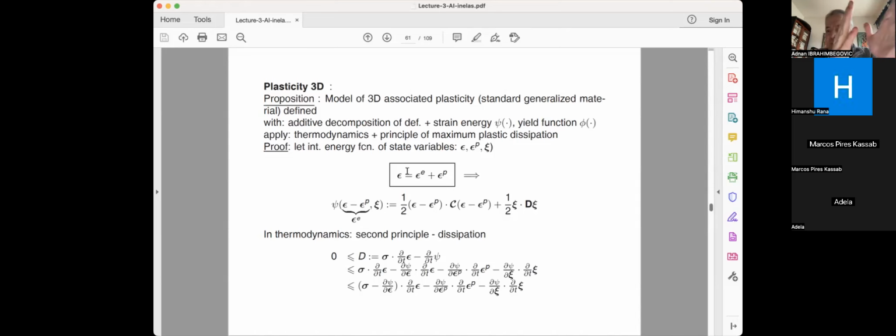As I said, for example, plasticity of metals is most about shear, because Tresca and von Mises and so on are about that. Then if you go to plasticity of cohesive materials like concrete, it's mostly tension and things like that. So each and every component which is representing a particular mode of deformation can be split into elastic and plastic. That's the first ingredient.